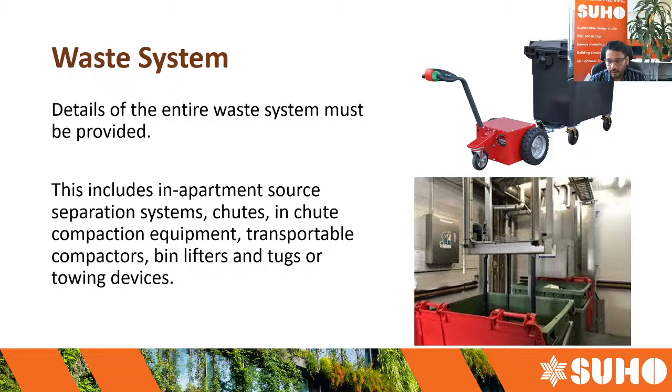So basically, if we are proposing a waste management plan and we say that the building operator has to take the waste from the bin store to the collection point, then we also have to mention how he will take that waste bin. Supposedly it's a big bin, so definitely he can't carry it easily by hand. So he needs some kind of supporting equipment. We need to mention that in the report.